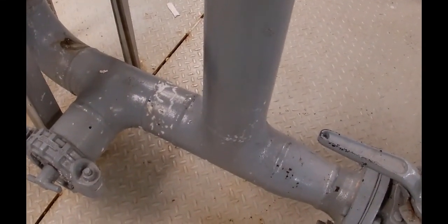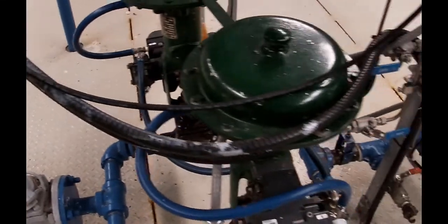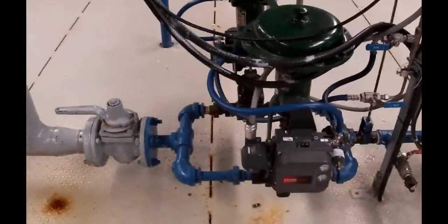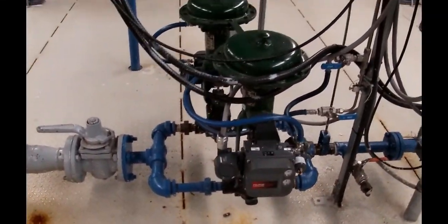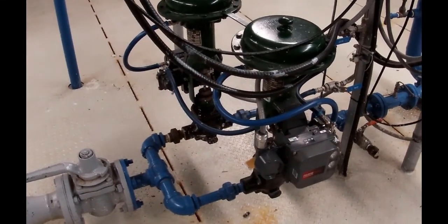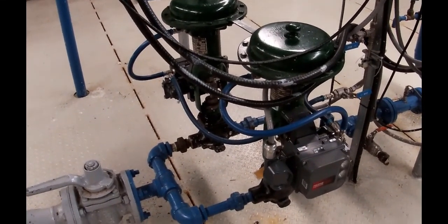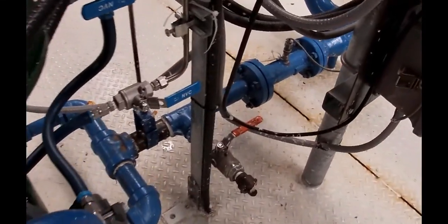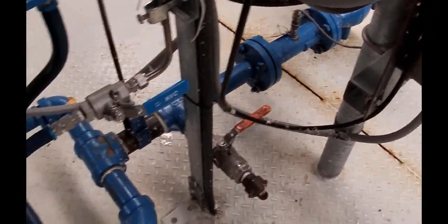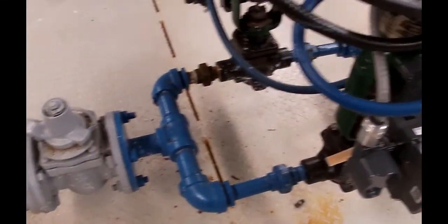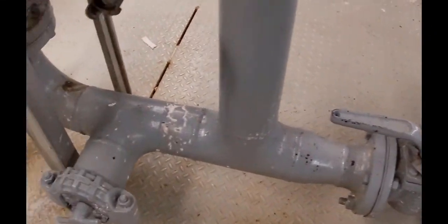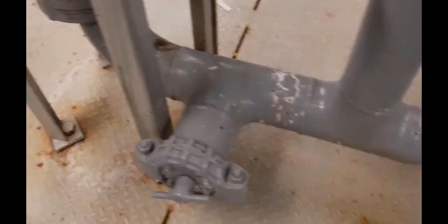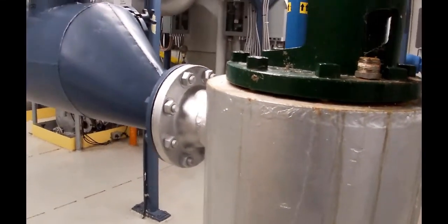down to 2.2. So we've got two valves, back up here, two valves, split range, and they're overlapped to one another to give a better turn down. There's a turbine flow meter back down in here, measuring the flow of the white water. The white water comes through those valves, mixes with a 2.65, up through a mixer, and then it heads to the head box.